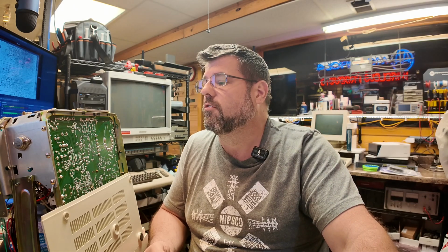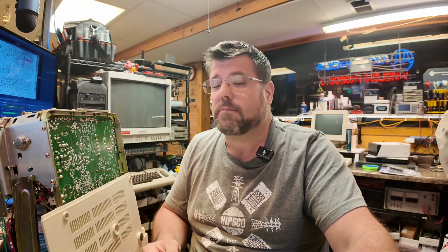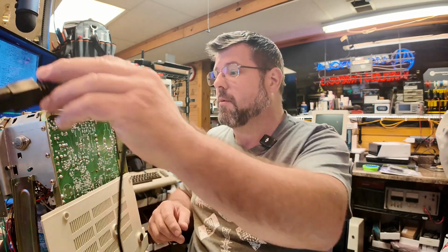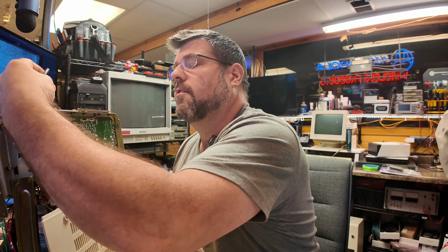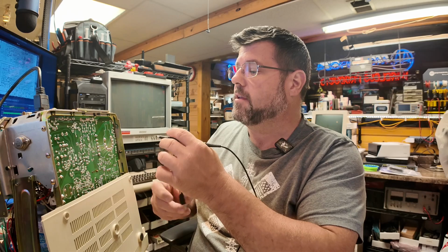Well, I switched the switch back and forth, and nothing changed, including the output of the switch, which is an extremely low voltage. So what I think happened is, over time, the switch is corroded internally and it's not making contact anymore. Now I can show you what it's doing here. If we plug this monitor in, everything is still on. I hear the screen warm up here. And if I take my probe